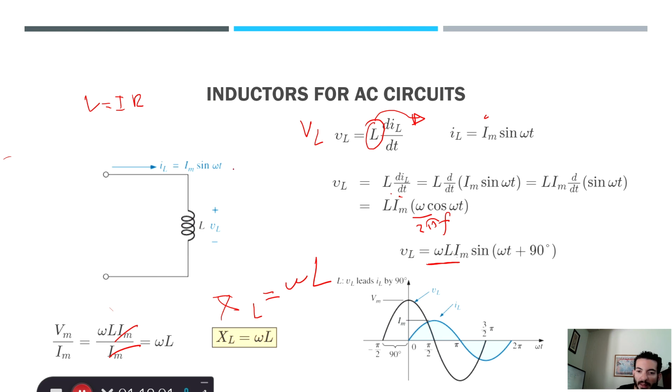First of all, there's an offset of 90 degrees. After you differentiate the function, your answer is going to be cosine of omega t. But if you remember the trigonometric identity, cosine of omega t equals sine of omega t plus 90 degrees. So to plot them, we can simply plot a sine wave with the new amplitude and an offset of 90 degrees.